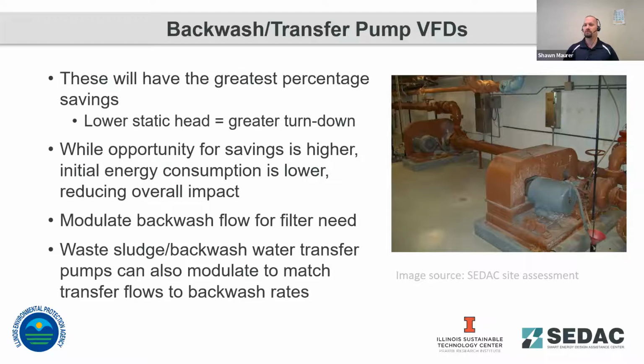But if you don't have demand charges on your plant, or the run times of these pumps are pretty low, this may not be a VFD opportunity for you, but it's something to look into. So looking at modulating the backwash flow for your filters: do you need to have full pressure for a filter backwash, or is it just enough to break the filter materials up and flush out materials? The duration of backwash is something we'll get into in the future.